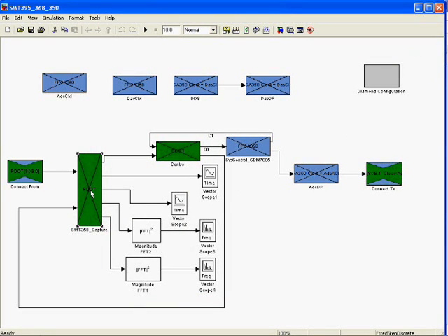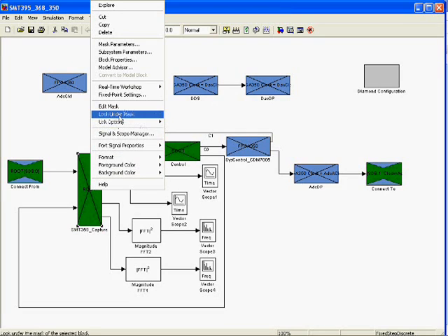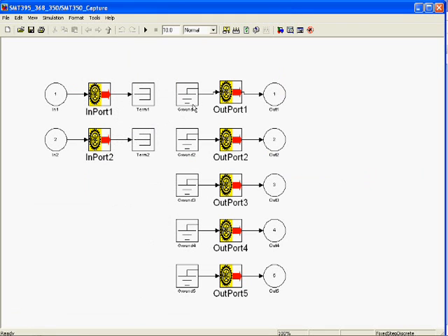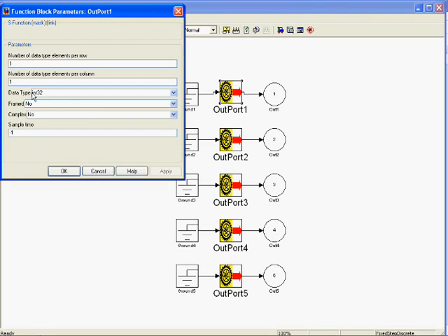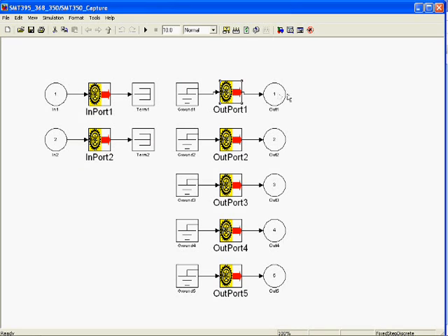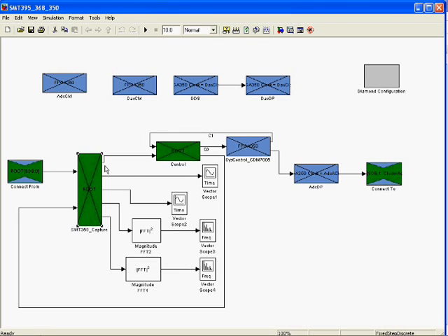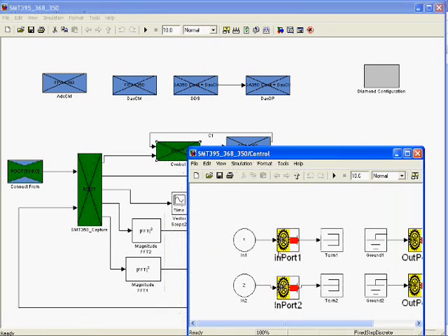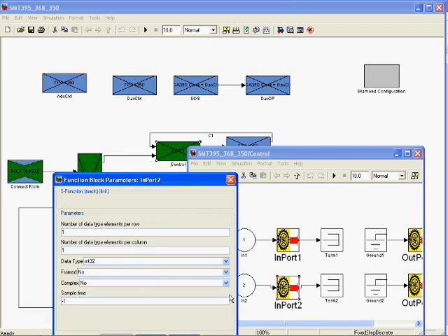When creating DSP pre-built tasks, care should be taken with data types for input and output ports. For example, here the SMT350 capture task has data type INT32 for output port 1. Therefore, the input port 2 on the control task should have the same data type. This is shown in the video.